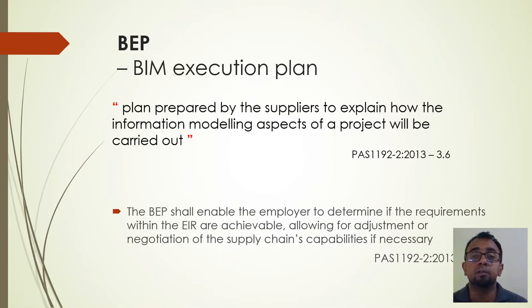It is resubmitted by the supplier to the employer, confirming the whole supply chain's capability, and also a thing called the master information delivery plan, which shows how different parties will contribute in terms of information, and that the relevant parties have agreed and committed to this BIM execution plan.